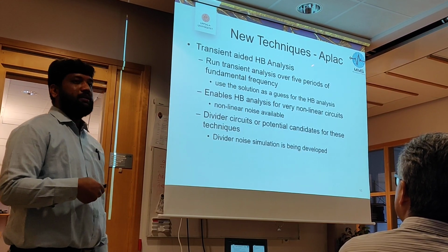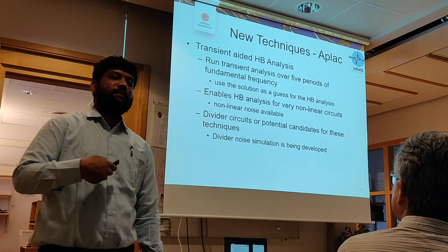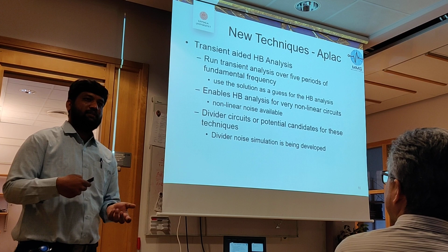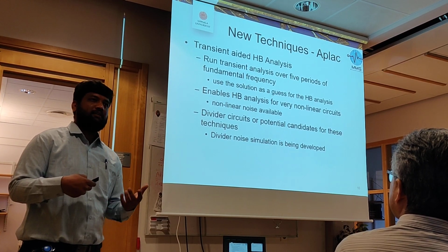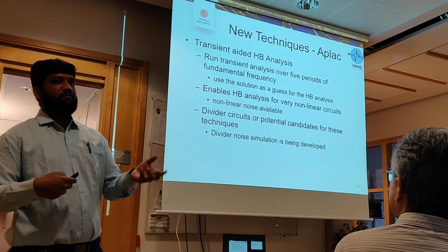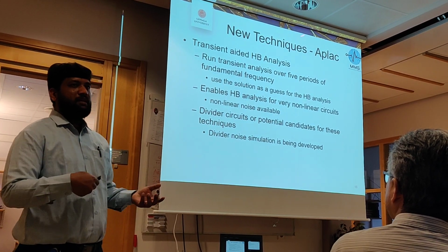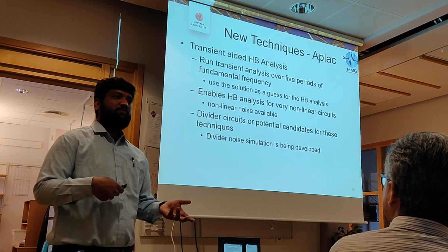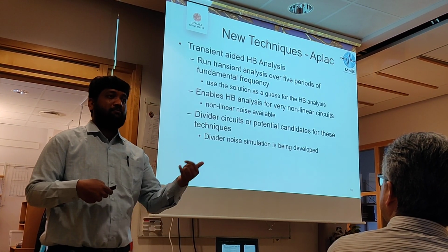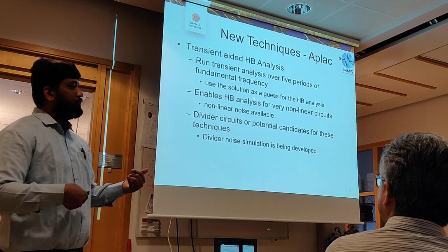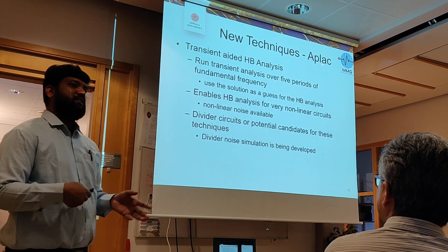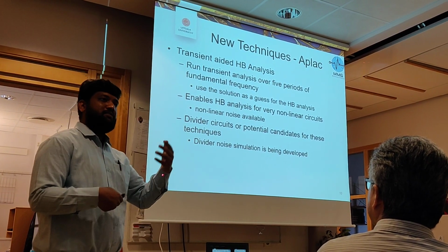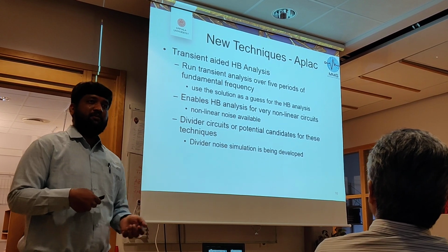It is a very intelligent model, but the problem with this model is the vendor has to provide an APLAC model for your design. Say you are designing an amplifier with respect to one company, say Philips, with some FET model. That vendor has to provide this model for your particular tool. Then you can make a good analysis. Or else you should look at the data sheet and change the parameters of existing models like the TOM model or any Gummel-Poon model. Any of the existing models, you have to change the second-order parameters and then you can use it.